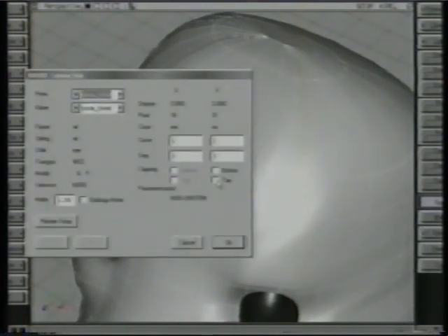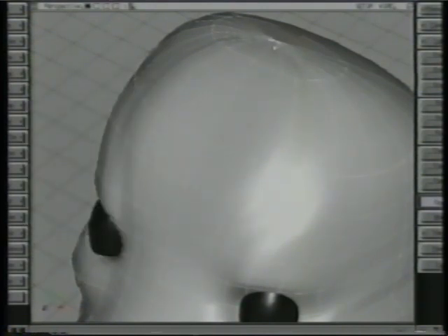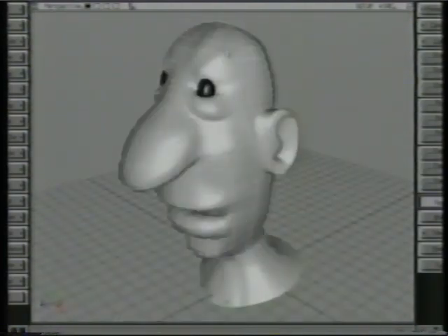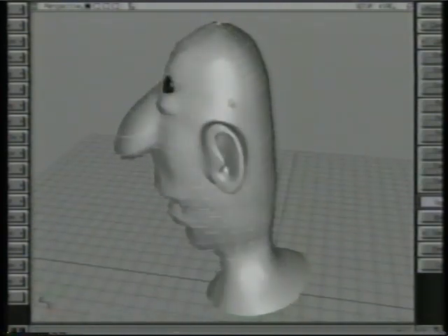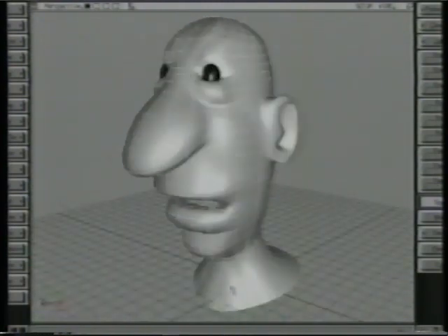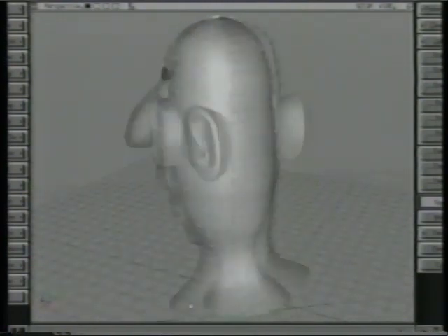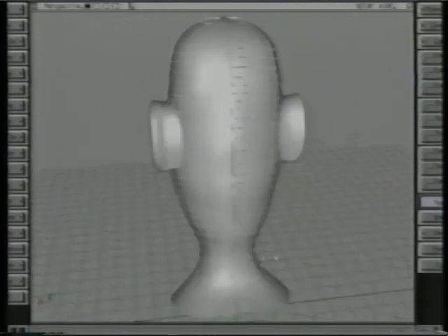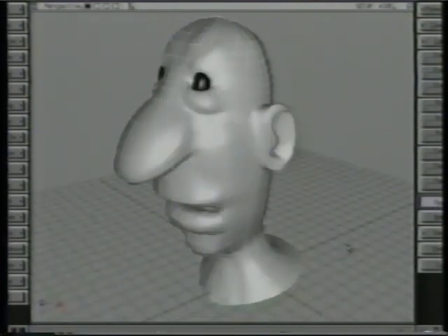Otherwise you can just go into here and turn on capping at the top, and that will do that. So this pulls a little bit because of the special oval shape, so I'll just undo that. So it has a normal top to bottom layout. I have edge flags on so you can see that the U edge is on the bottom and the red goes up the left side, and that's how it should be for texturing, because the bottom of the texture map will go along the green or U line.